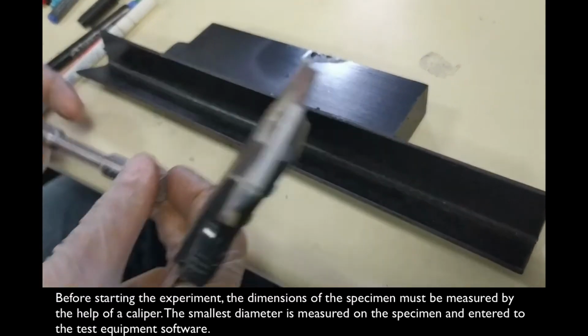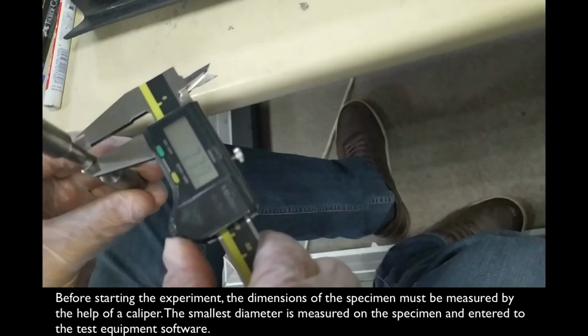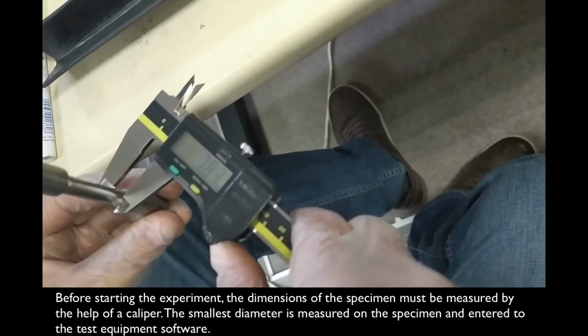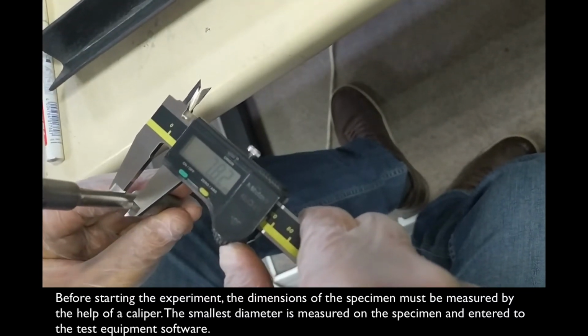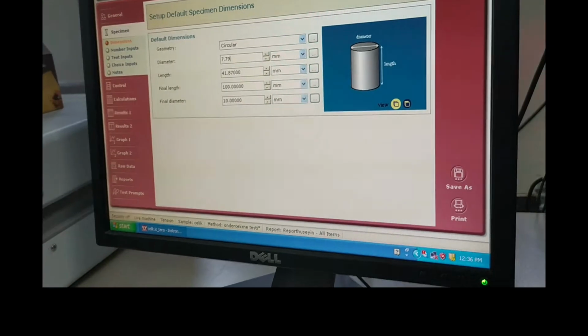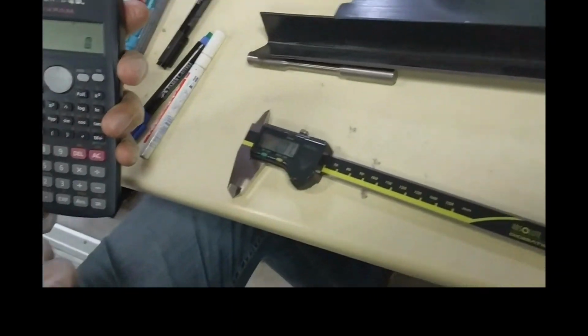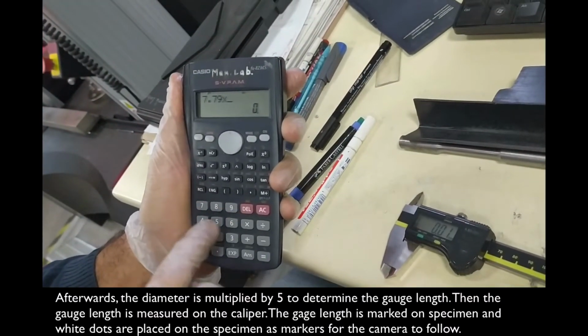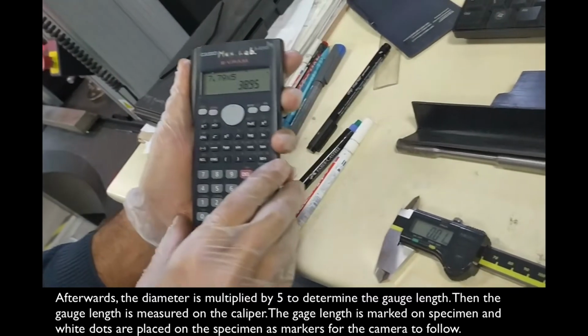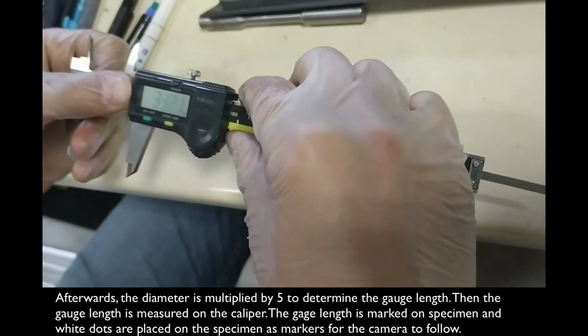Before starting the experiment, the dimensions of the specimen must be measured with the help of a caliper. The smallest diameter is measured on the specimen and entered into the test equipment software. Afterwards, the diameter is multiplied by 5 to determine the gauge length. Then, the gauge length is measured on the caliper.